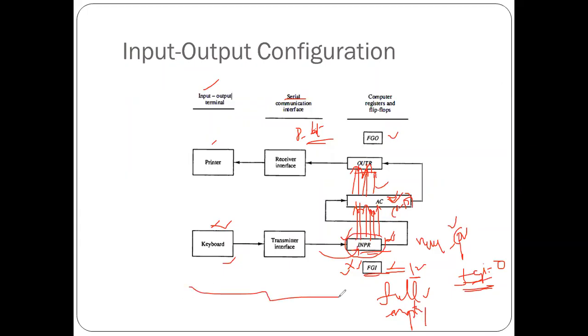That is the input side. Now, for the output side, in an output operation, the contents to be printed onto the printer or output device are available in the accumulator. The accumulator holds the data to be sent to the printer. The lower 8 bits of the accumulator are placed onto the output register in parallel, and the flag is cleared to 0.